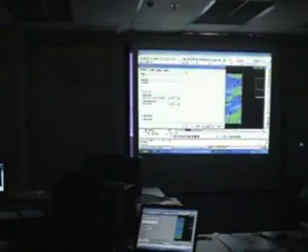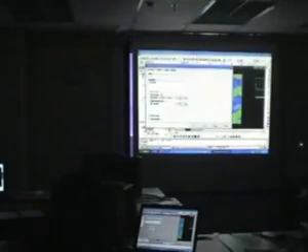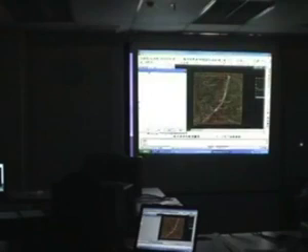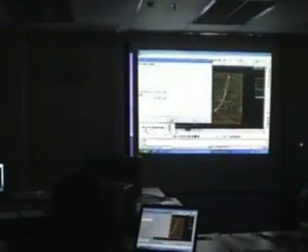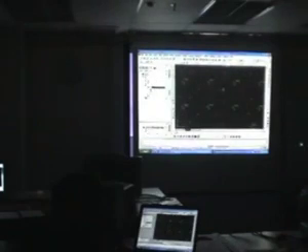You can see how it's updated automatically in the background. Now these are all the triangles, colors. If we want to see another one, say I try slope arrows, apply. Now you see the contour lines have changed color and there are slope arrows. I don't think you can see it, so I'm just going to zoom in so you can see the slope arrows. Still being updated. Okay, these are the slope arrows. The slope arrows basically indicate how we are going downwards this way.